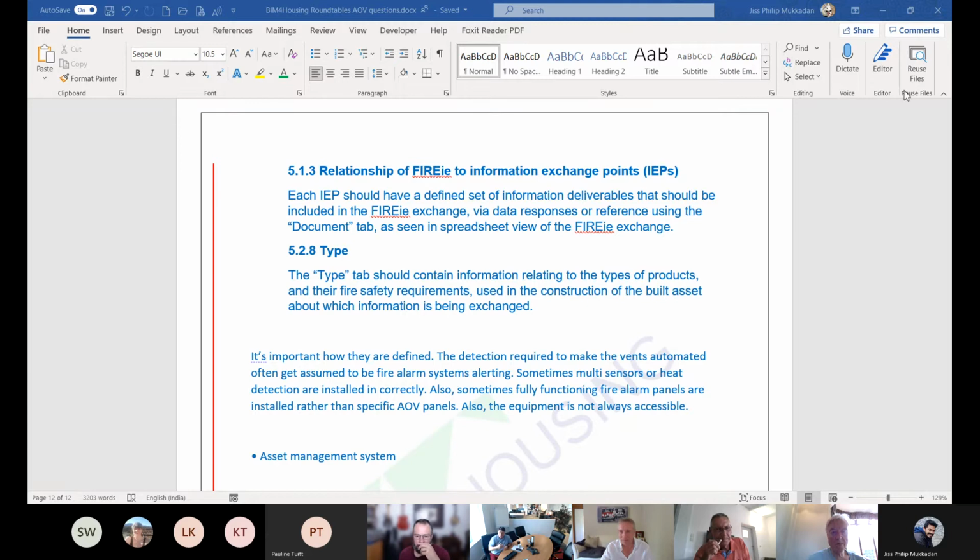And I think it's that as well, that what else is going to impact on equipment that people are putting in. It may not be that you're changing the equipment, it's the fact that you're putting something into that building, like that suspended ceiling, that completely nullifies the fire compartmentalisation, and it all has to be pulled together. And we see it on a regular basis, certainly on refurbishments, where great on the build, it's probably been signed off at some stage, but it doesn't take long for a building to be refurbished. And what is the impact of what they are doing on there? So it's not just changing specifications on equipment, it's also changing specifications for the building.